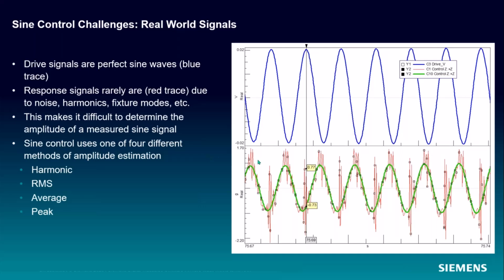What my accelerometer is going to measure is this red noise stuff. It has all the harmonics of the structure. If there's any rattling or impacting that happens, you get all this noise that's feeding into the control accelerometer from different frequencies. And typically what we want for sine is to understand what's happening at the exact frequency of excitation.